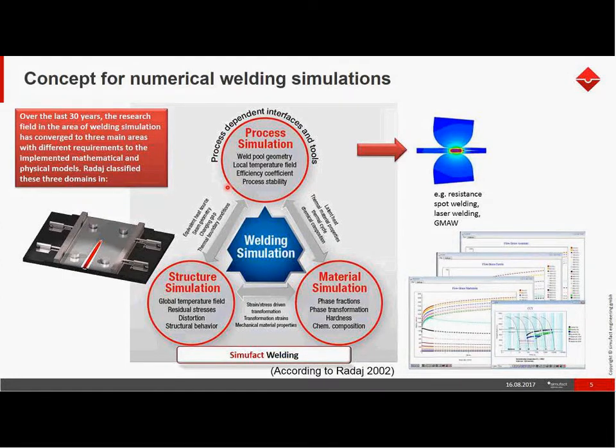For instance, when you have laser welding, you can have things like a keyhole that is building, and you have multiple reflections inside the keyhole. All these things need to be considered in a simulation. These kinds of simulations are processed with CFD, or fluid dynamics simulations. There are only a very few commercially available solutions for this, and it is often difficult to simulate these kinds of effects in an entire simulation.